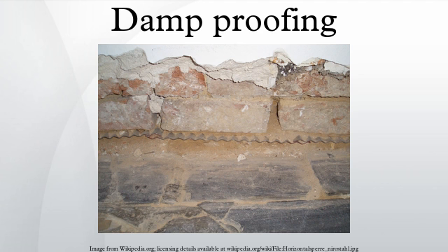Integral damp proofing in concrete involves adding materials to the concrete mix to make the concrete itself impermeable. Surface coating with thin waterproof materials provides resistance to non-pressurized moisture such as rainwater, or a coating of cement sprayed on, such as shotcrete, can resist water under pressure. Cavity wall construction, such as rain screen construction, is where the interior walls are separated from the exterior walls by a cavity. Another method is pressure grouting cracks and joints in masonry materials.